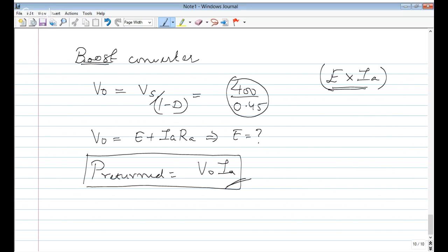Loading of a cable is done in order to increase its inductance, increase its leakage resistance, decrease its capacitance, achieve distortionless condition. So Naveen, in case you want to achieve distortionless condition, RC should be equal to LG. That is the condition for distortionless transmission. I don't think it has anything to do with the loading. So I feel the answer should be only 1. It should not be 4. Oh, only 1.